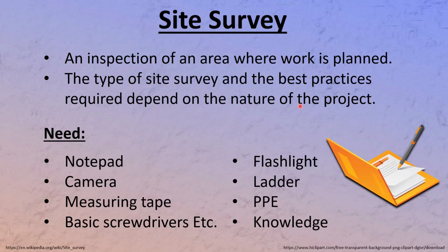So sometimes you're going to just go and say, yeah, okay, I can see there's a drop ceiling. Yeah, there's a cold air return plenum, so that means free air. We need some FT6, make a note. FT6 wiring is required. And there is some old Cat5, I can see wires. So those wires have to be replaced. How easy is it? Do we need any special equipment? Do we need to rent a lift, or do we just get away with the ladders? And are there any obstacles, maybe a difficult passage to get the wires through from one floor to another for whatever reason? All those notes have to be taken.